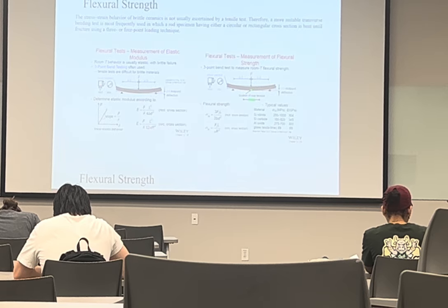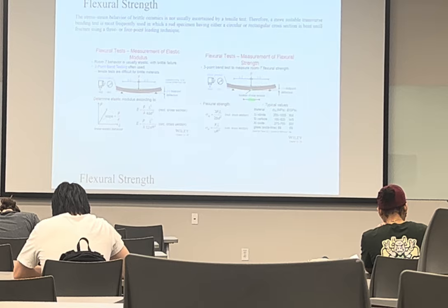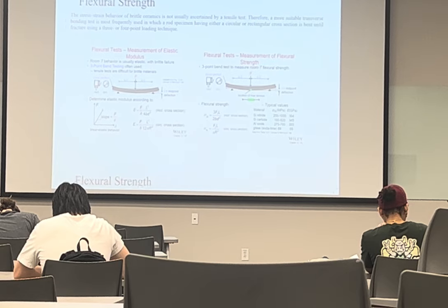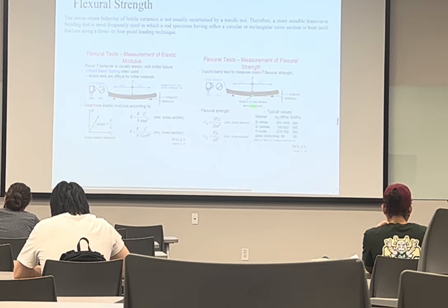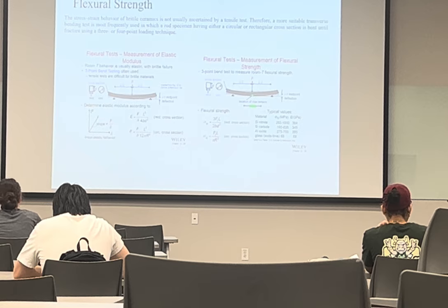Why? Because we cannot do the tensile test on ceramics. They are so fragile, actually, so brittle. So it's not practical to perform tensile tests on ceramics. Instead, they use a bending test, and based on that, they can measure the flexural strength of the ceramic.